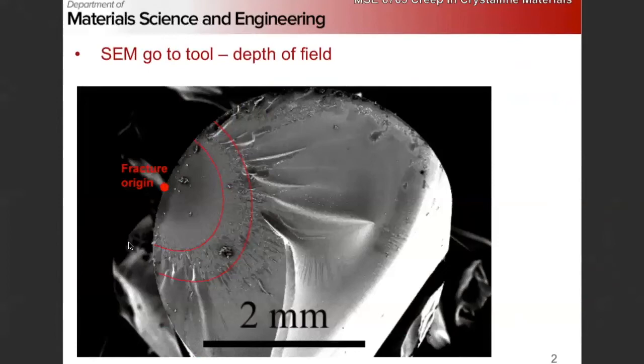But basically, the wider your angle, right? So the closer your objective lens gets to your sample, the narrower your depth of field is going to be, right? If you think about a light microscope going up against the fracture surface, that angle approaches 100. Well, it's half the angle, so it approaches 90 degrees, right? Or your full angle approaches 180. So you essentially have a depth of field that's only a couple microns, right?